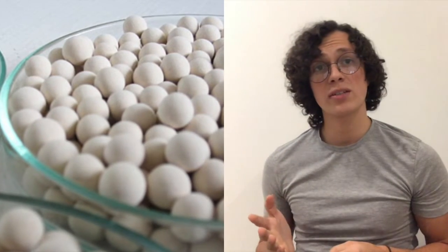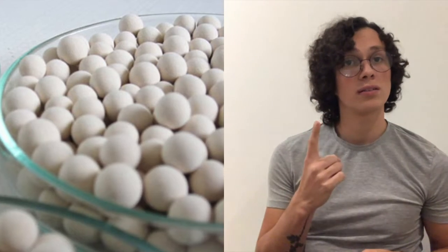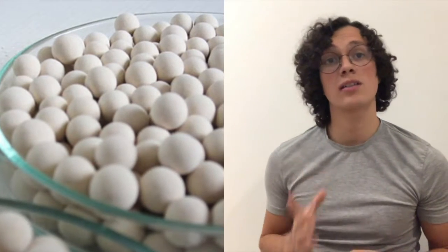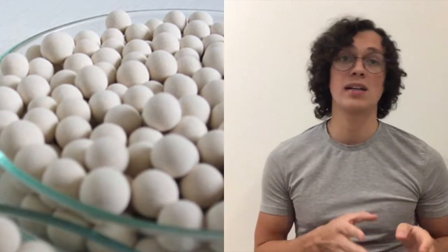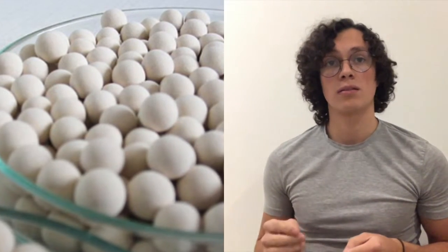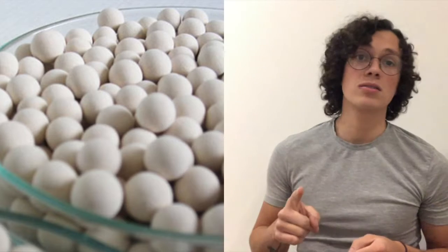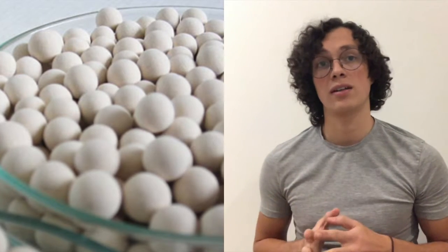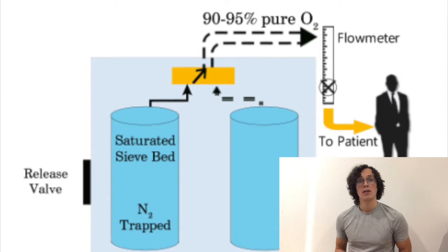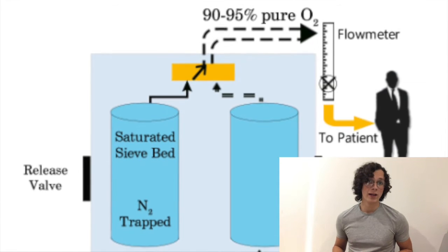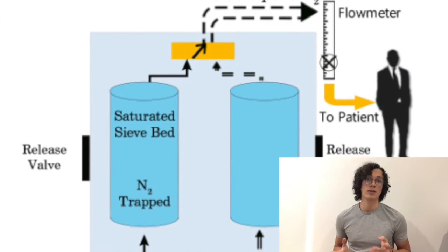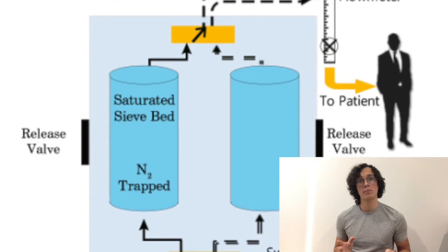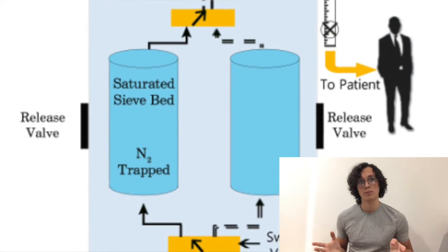Based on this information, we grab one single bead of zeolite. This is our proposed model, and from this we can calculate the time until saturation and when the molecular sieve bed has to change to the other one because this one is saturated. It is also assumed that there are no reactions and that diffusion is kept constant and in one direction, as molecular sieve beds only go from up down or down up.